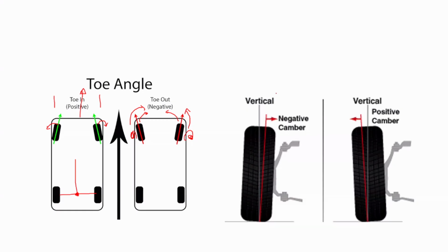So and also camber. Camber is the angle in between vertical direction and the tire's axis, right? So camber also depends based on the driving condition, but normally we prefer negative camber in on-road driving, where it can support the traction, especially while taking corners, right?